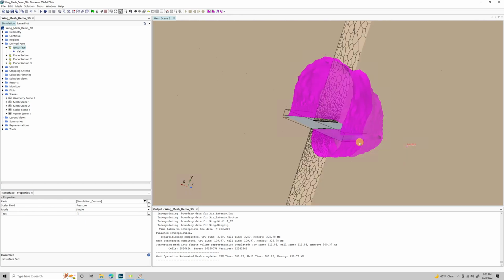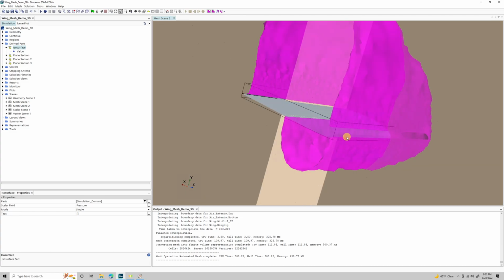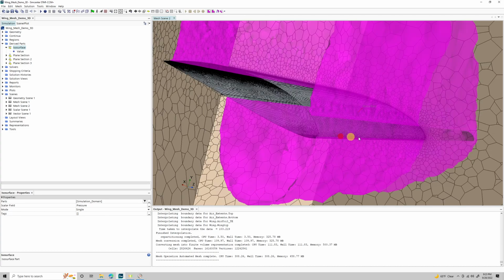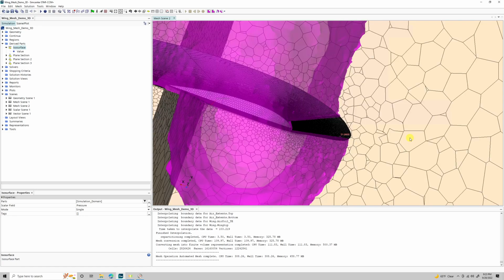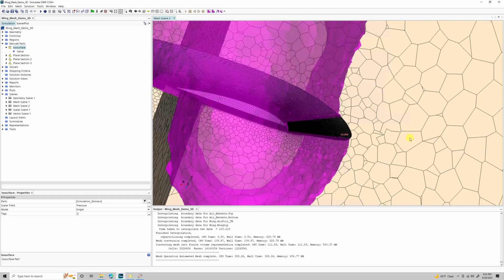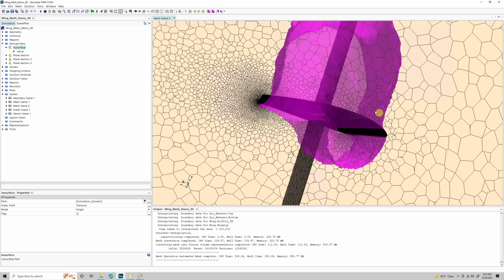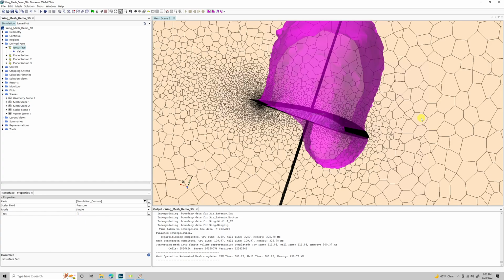And at the leading edge of the airfoil, where we expect a stagnation point and relatively high pressure, we see that there's kind of a slot in this surface. Exactly what we would expect to see. And it is a little bit lumpy just because the mesh is relatively coarse, actually.